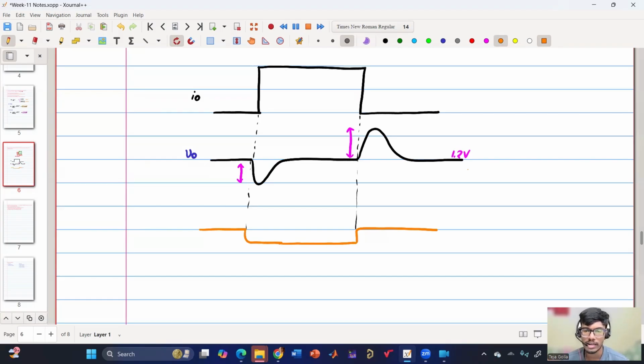it will not only work at 1.2 volt, right? It will have a certain threshold. So now what I'm trying to do is I'm taking advantage of that threshold and making sure that my output voltage is within that threshold, so that the processor will still perform at that high performance, and then there will be no performance issues when I'm playing a game on the application.